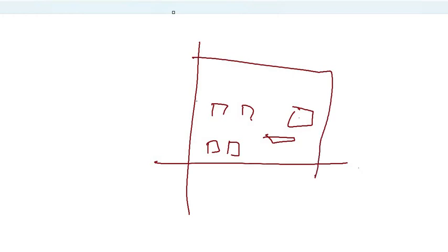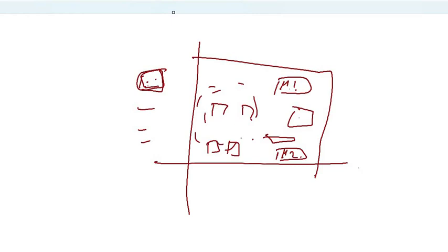Now, before you generate this, as I said, when you dig into your schematic, you would figure out that it has one or two levels of hierarchy. So whatever the levels of hierarchy, you need to do a floor plan of that level of hierarchy first. Put it in a PR boundary, and then when you come to this top level, you'll be generating it. So you will have a module 1 here, and say a module 2 here, and these are all the other instances at this level of hierarchy.